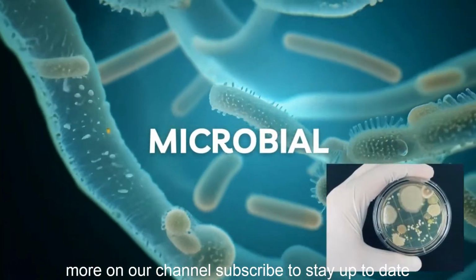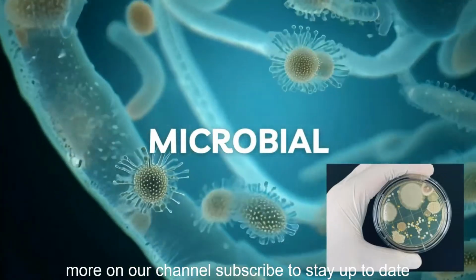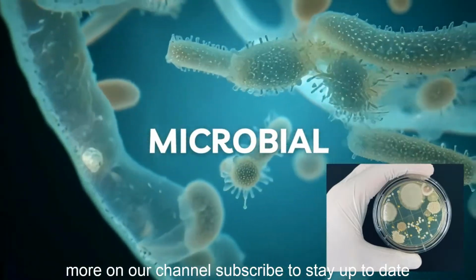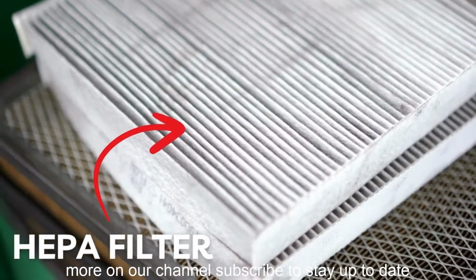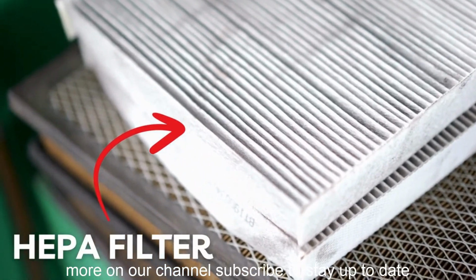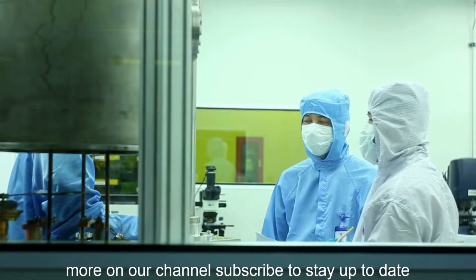Microbiological contamination. This refers to contamination by bacteria, fungi, viruses, and other microorganisms. Annex 1 emphasizes the importance of cleanroom design, personnel hygiene, and sterilization processes to control this risk. For example, it specifies requirements for air filtration, HEPA filters, room classification (grade A, B, C, D), and the validation of sterilization cycles.